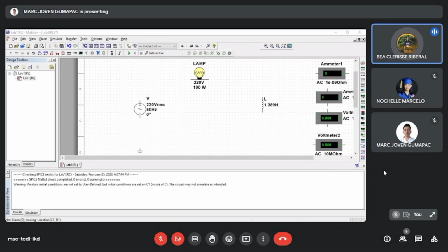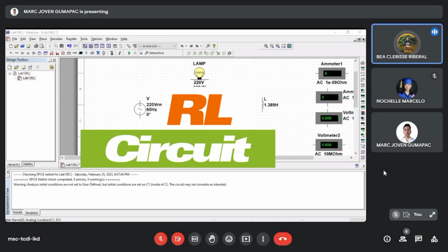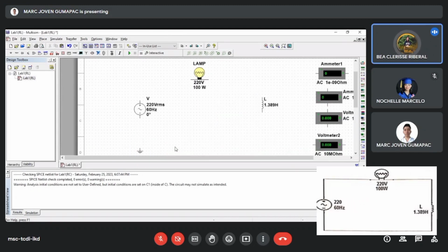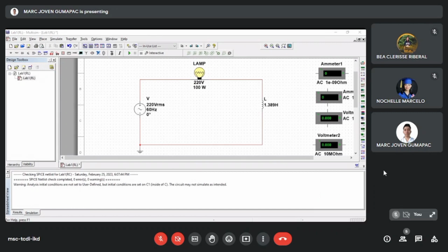Moving on to the second part of the experiment, the RL circuit. Connect the circuit shown in Figure 4. Measure the total current and the current across the lamp and across the 1.389 Henry inductor. Turn on the run button to simulate.